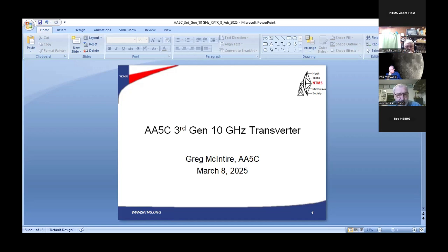Simple interfaces, power, PTT in and out so I can use digital modes, 2-meter IF, and then the RF connector. Always include a front panel meter for relative transmit power output reading, so you know you're getting out when you're in the field, and then have some fun building. I like to build things, and this was right in line with that.